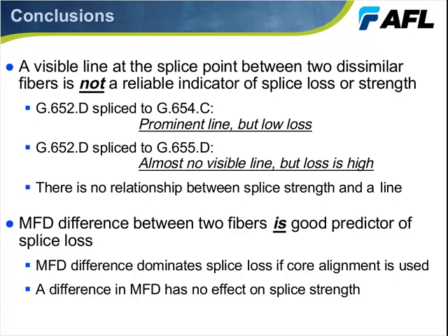On the other hand, if we know the mode field diameter difference between two fibers, that is a very good predictor of splice loss, as we've seen in this case, because that is actually related to the transmission or the coupling loss at the splice point. So with that, that concludes this presentation, and I want to thank everybody for participating. And thank you, Doug.